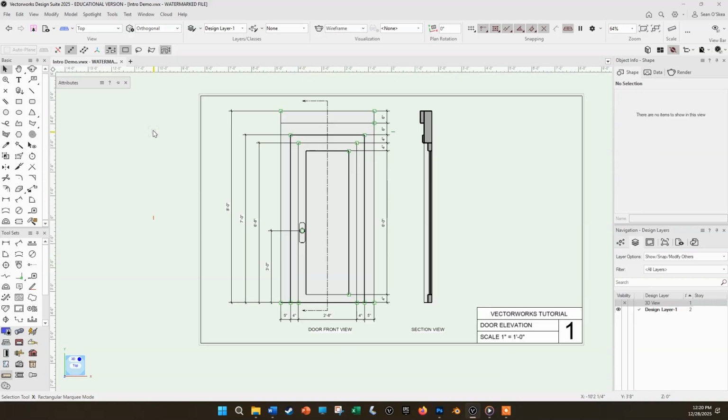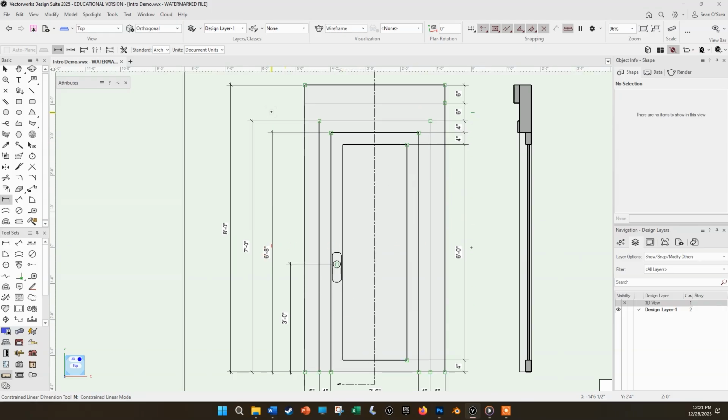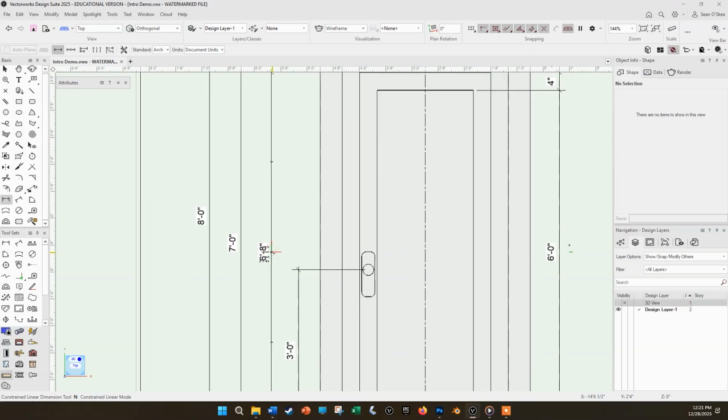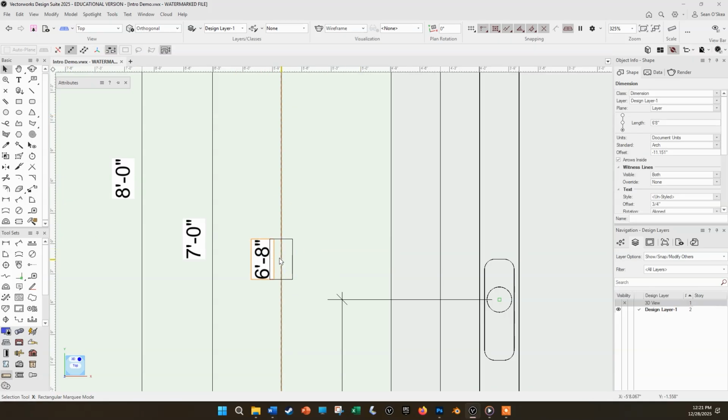We've covered a lot in this video, and our drawing is ready to print, but let me show you one more bonus thing about dimension lines that can save you room on your drawings and confusion in the shop. Notice that the dimension text is stacked above or to the left of the dimension line by default. Back when I hand drafted, I always preferred the aligned dimension that placed the values centered directly on top of the line. Not only does this save a lot of space with nested dimensions, it also eliminates any confusion as to which number goes with which line.